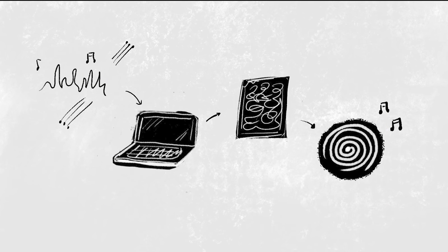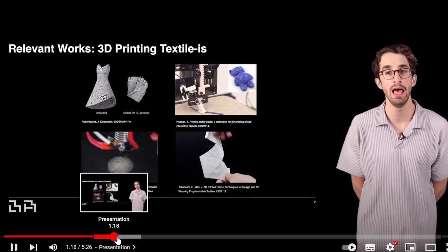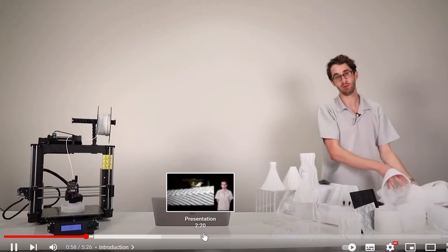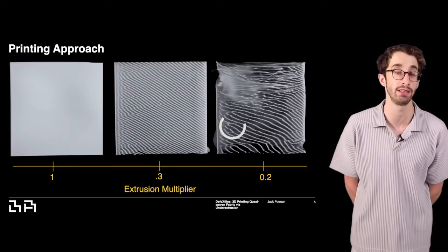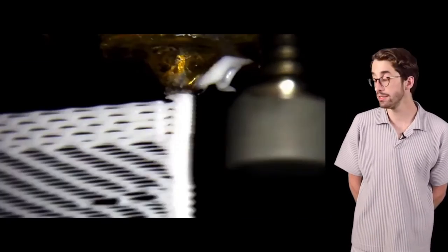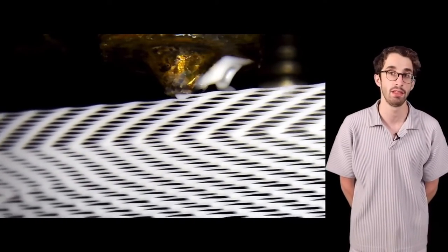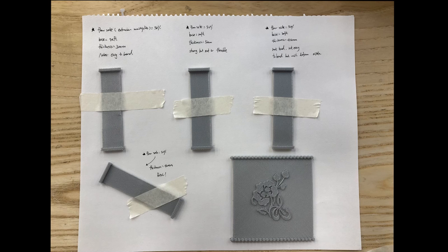It is a challenge to discover what kind of structure will make it feel like real textile. I am still learning this, but currently I tried the following methods. The first one is from MIT Media Lab called Deflex. The method is adjusting the flow rate of the 3D printer, and if we adjust this parameter to below 50%, we can print a rectangle as normal, and then we have a flexible feeling. I tried different thicknesses of rectangles and flow rates, so the flexibility will be different.